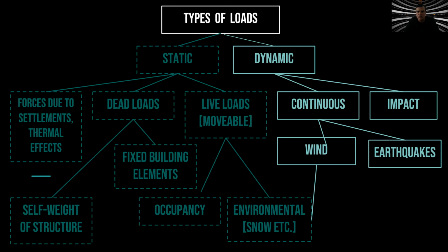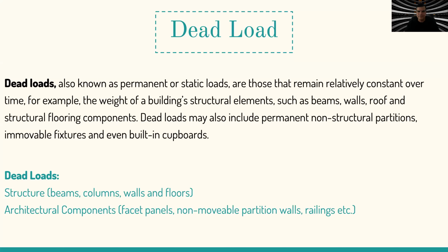After, we have some loads that are due to settlements or thermal effects. For example, in a bridge, because it's a very long structure, if the sun is hitting in the morning, after in the afternoon, the bridge will become bigger. A long bridge can change a lot. It can become 1 foot longer. It will move. However, after when it becomes cold at night, it will retract and become smaller again. Well, thermal effect is important, especially in long structures.